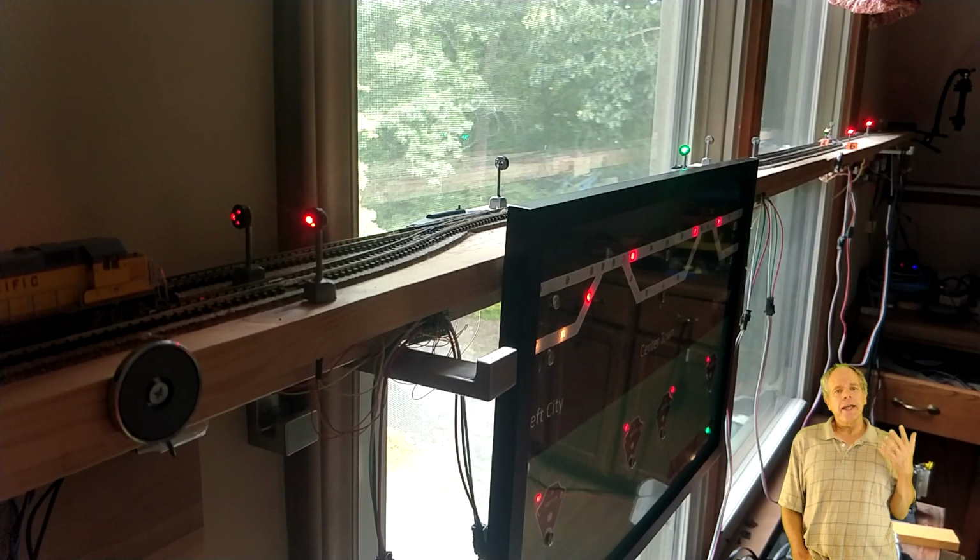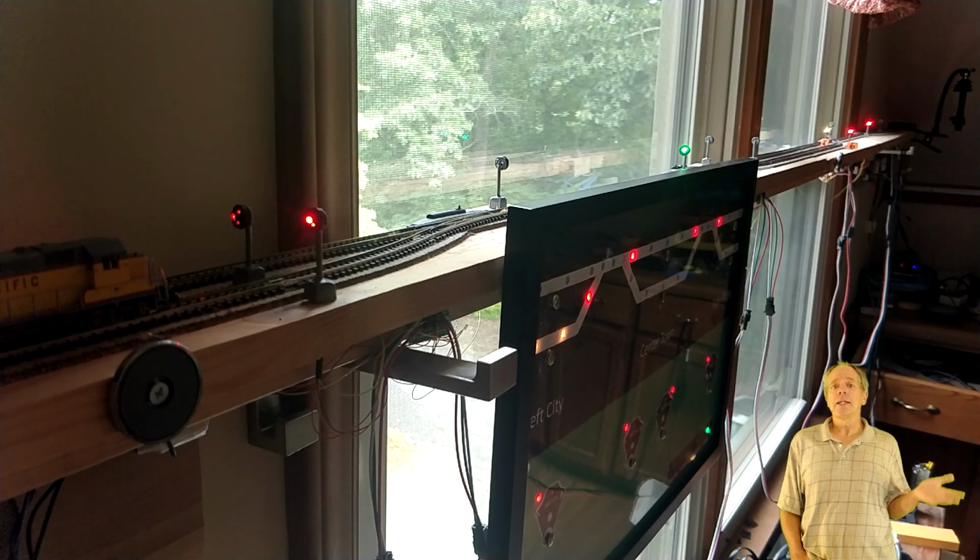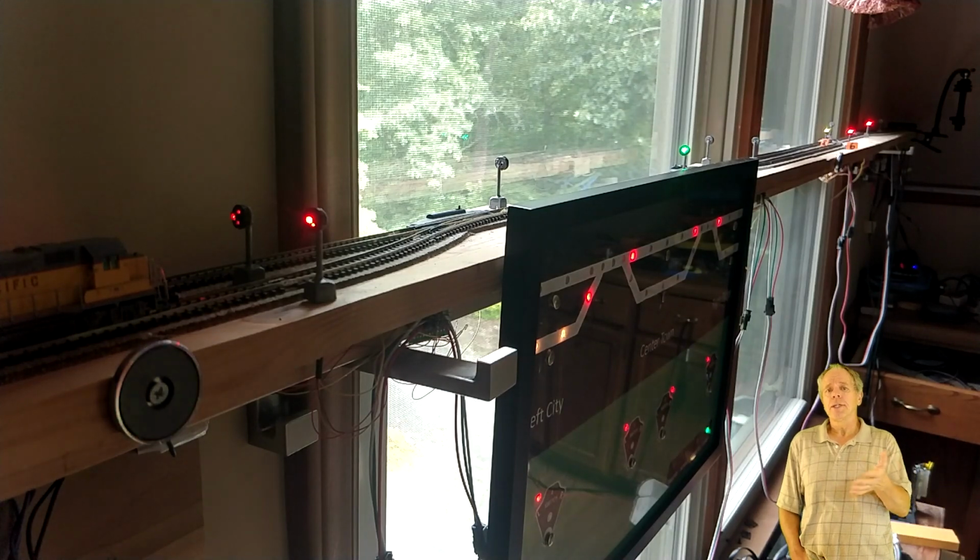Now I change signal 810 to halt, and as a result signal 808 changes to slow. Signal 804 remains on track speed as there is no need for the train to slow down in the first part of the ABS zone.